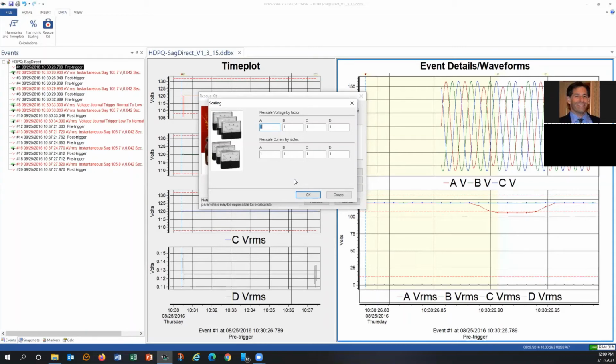So maybe a 3000 to 5 CT in addition to selecting, as an example, an RTR 2510 in the instrument. These are meant for cases where you had a big oops in the field, you forgot to configure the instrument correctly and account for all the transducers in the measurement chain.